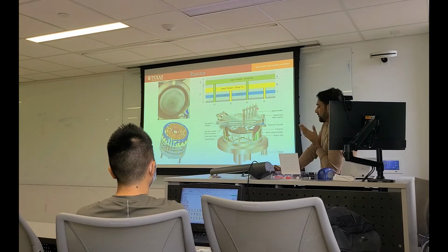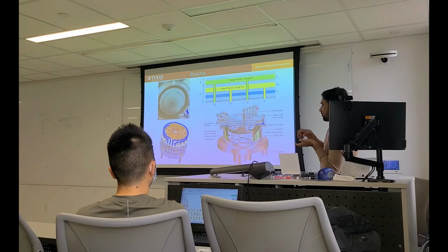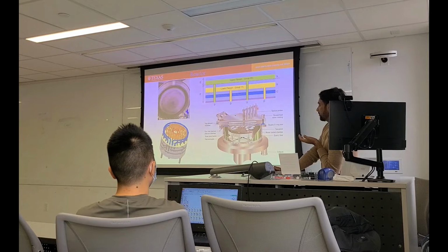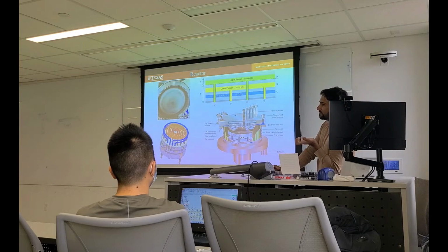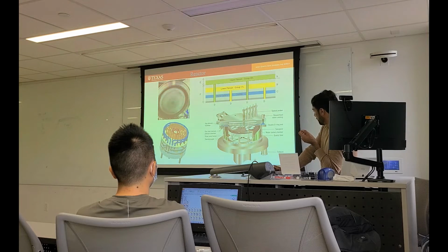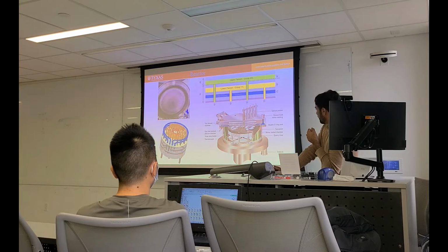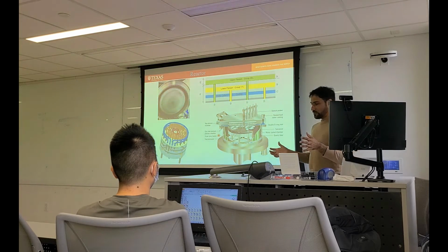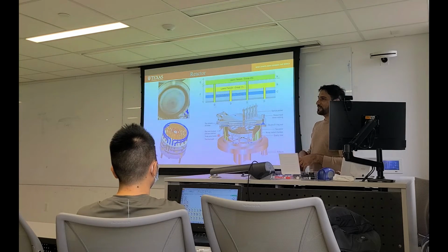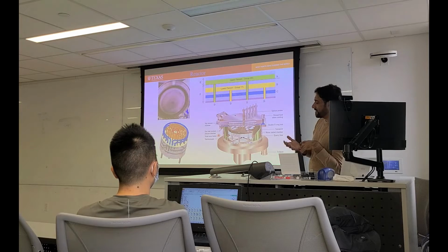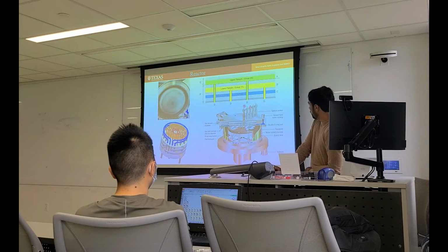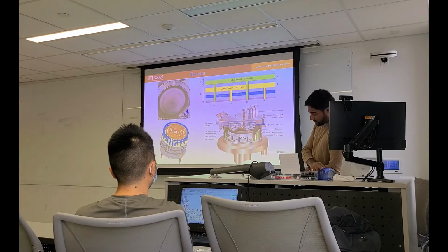These optical probes are used to tune the heating to make it uniform through all zones. Otherwise, your substrate at the inner side will have different morphology than the substrate at the outer side. You have 4 separate power supplies to control these heaters, and then this is the exhaust, which is connected to the vacuum pump. This is a quartz liner, to make sure the heating is very uniform inside the reactor assembly. So this is a very advanced reactor assembly. This is all about the shower head of MOCVD.